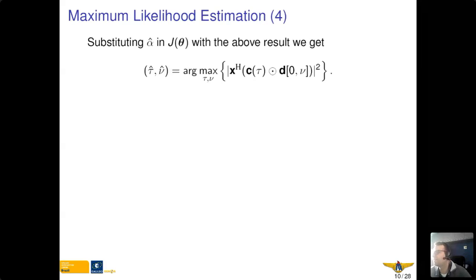We cannot further simplify this. But again, you can see this is cross-correlation, right? So we have cross-correlation of the received signal now with Hermitian. As the signal model is now complex, we have to take this into account. So this has to be the Hermitian with respect to the model of the signal that we're using for the correlation.